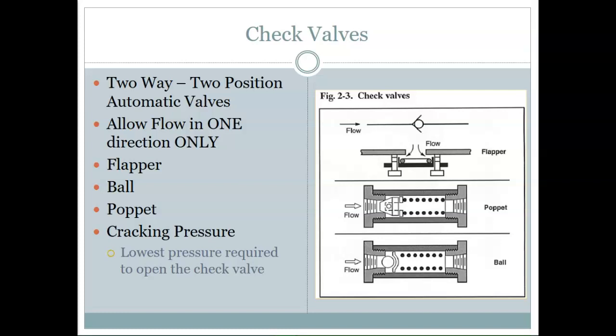So in order to protect your pipes, in order to protect your valves, in order to protect everything, the best way you can ever open something is by starting to do it gently. Because if you crank it open real fast, you don't know what's on the other side of that.